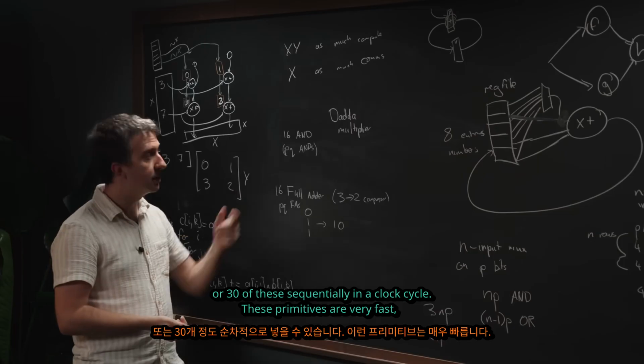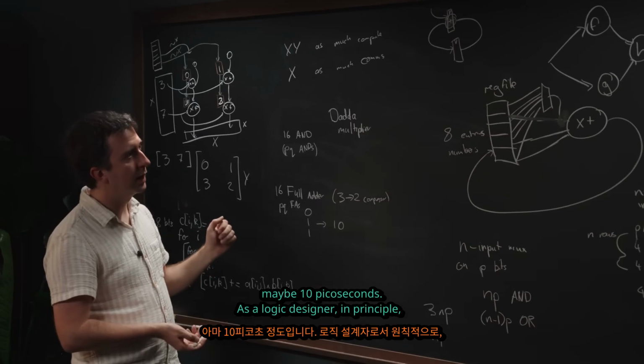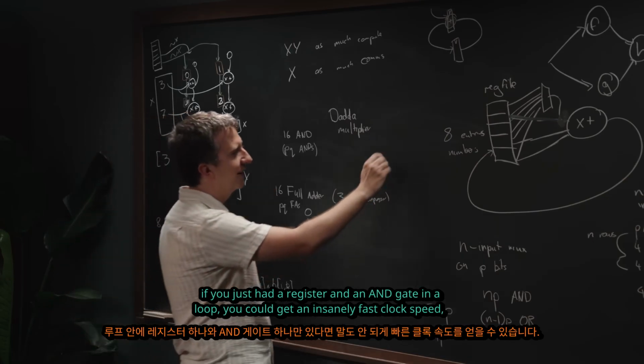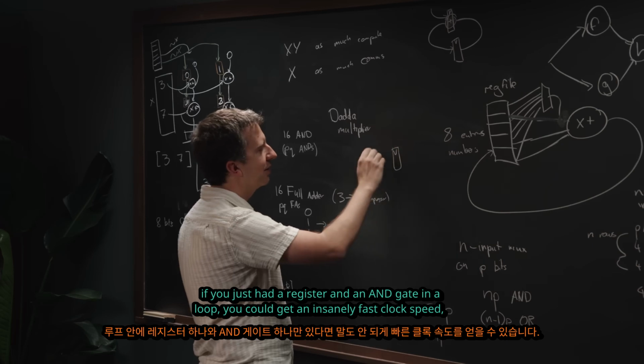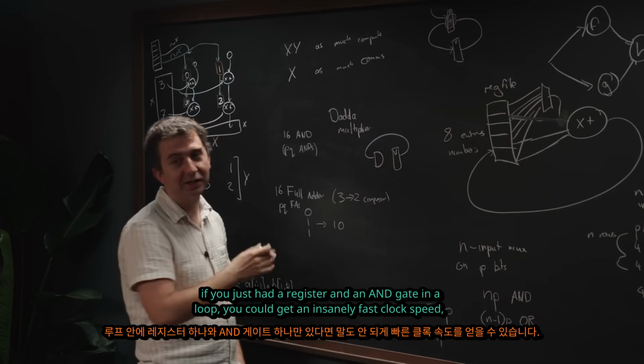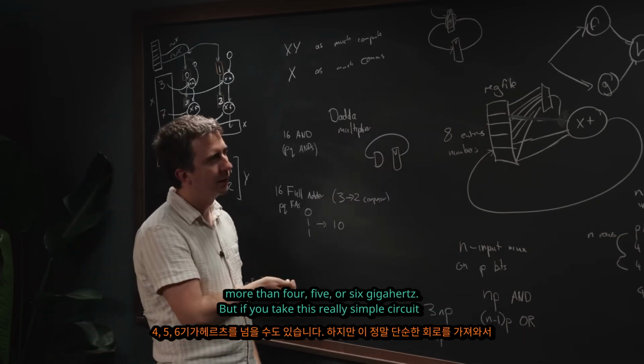These primitives are very fast, like 10 picoseconds. So in principle, if you literally just had a register and then an AND gate in a loop, you could get an insanely fast clock speed, more than 4 or 5, 6 gigahertz.